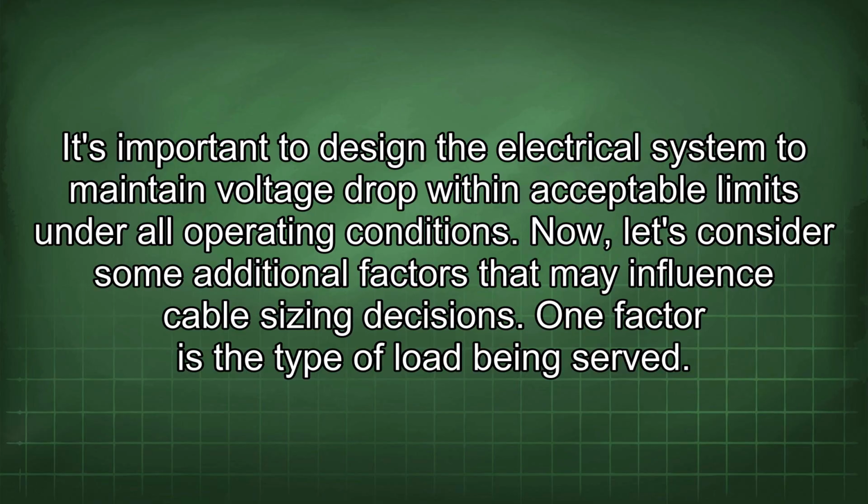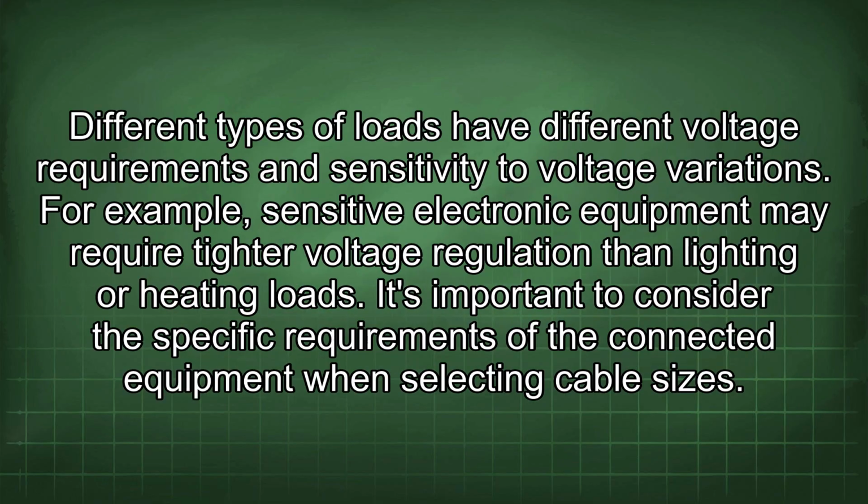Now, let's consider some additional factors that may influence cable sizing decisions. One factor is the type of load being served. Different types of loads have different voltage requirements and sensitivity to voltage variations. For example, sensitive electronic equipment may require tighter voltage regulation than lighting or heating loads. It's important to consider the specific requirements of the connected equipment when selecting cable sizes.